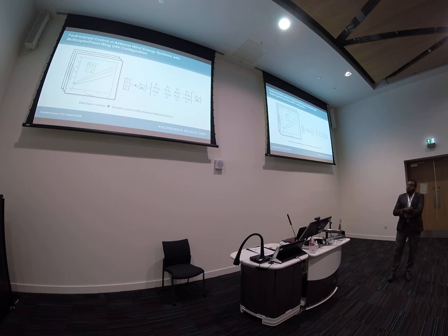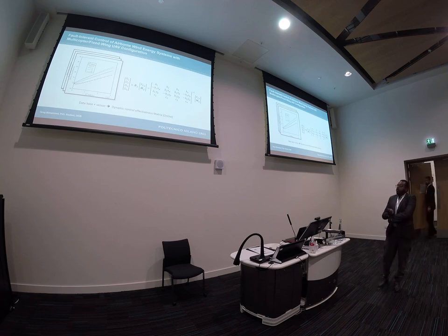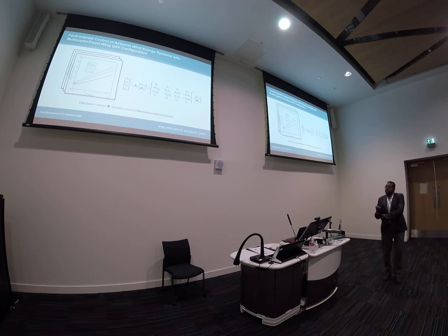Similarly, we also build a dynamic control effectiveness matrix for the quadrotor system. This matrix, denoted by BQ, will be used to transfer between the RPM of the VTOL system and the thrust and the moment of the quadrotor.